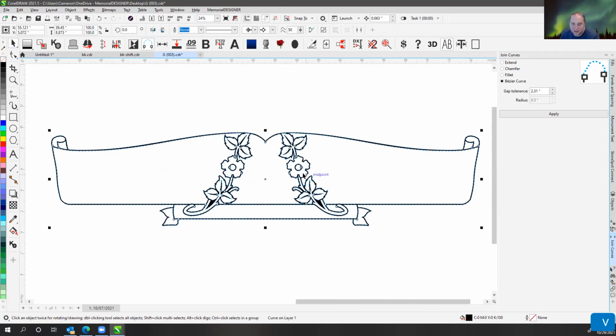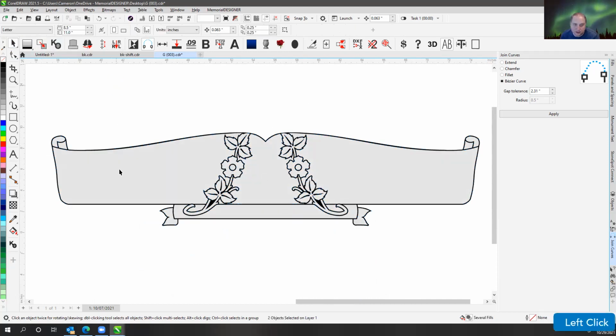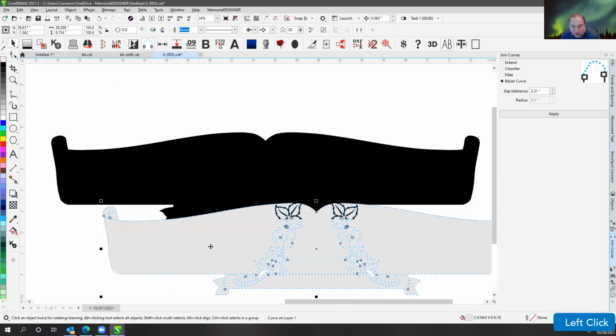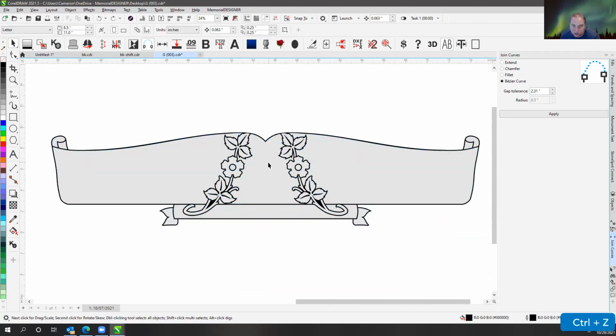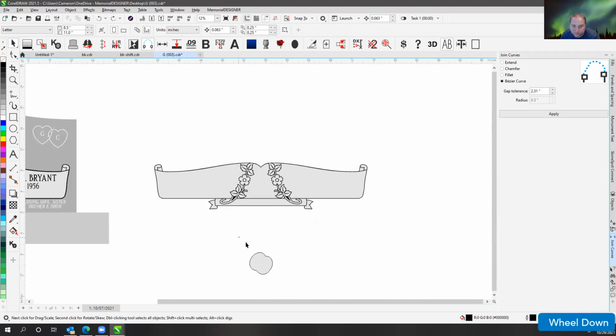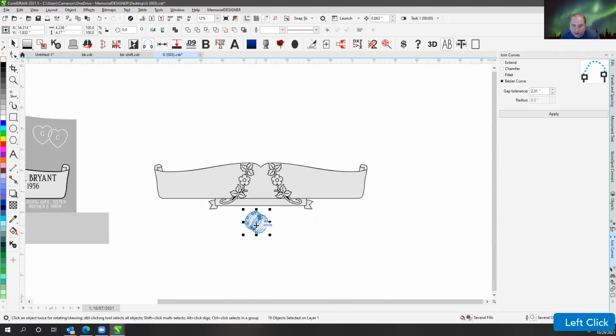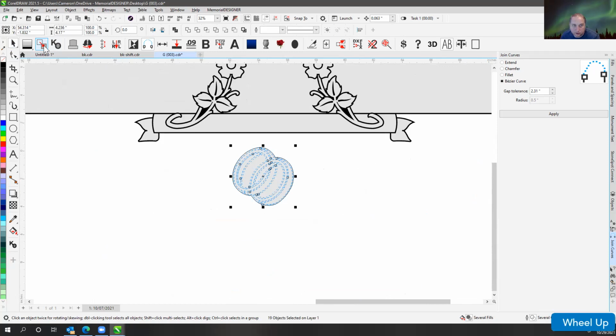It's now exactly the same on either side. I'd hit fill grayscale. What that does is it's going to break everything apart and then only combine these inside pieces, turn them 10% gray, and then give us just a black outline. That way it's going to fill correctly with the granite fills. And then I'd take this one and bring it back. Okay, so I will fill grayscale on this one as well.